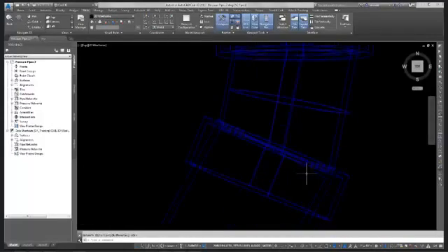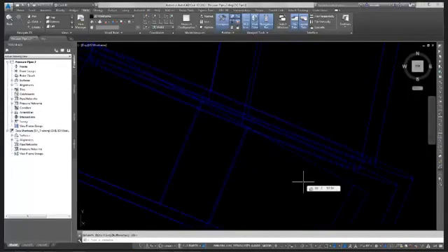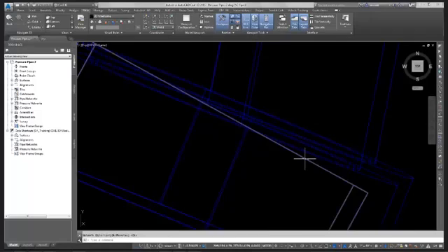So if you ever do your pressure pipe networks, make sure that when you put your angle of deflection in, you put it in at a 90, at a 45, or I guess 45 plus or minus 5 degrees, 90 plus or minus 5 degrees, because you are allowed that 5 degrees of deflection per pipe and still have it seal. So that's using from object.